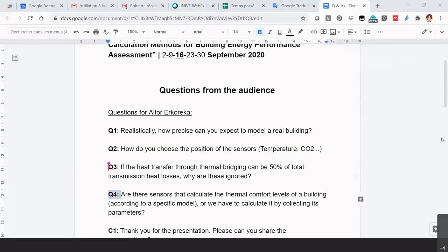And the good thing about the techniques you are learning here is that when you use the modeling approaches to obtain the heat loss coefficient of the building, which contains the UA value, it's possible to break the heat loss coefficient into the UA and the infiltration and ventilation heat loss coefficients.